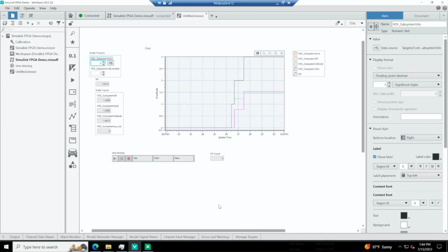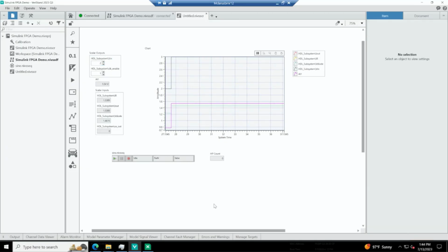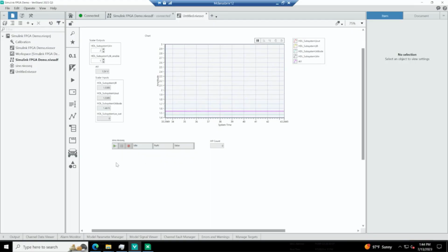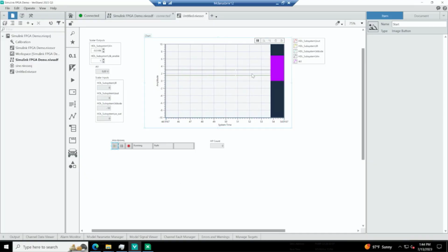Now, what'll be more interesting is in the response we saw in Simulink, I was supplying a sine wave of amplitude 10. In preparation for this, I created an RT sequence that'll deploy down to my target and set values similarly with a sine wave of voltage 10. So what I'll do here is actually start this, which will compile and deploy that file down to the target. So right now it's compiling, deploying, and pretty quickly we'll start seeing some very fast responses.